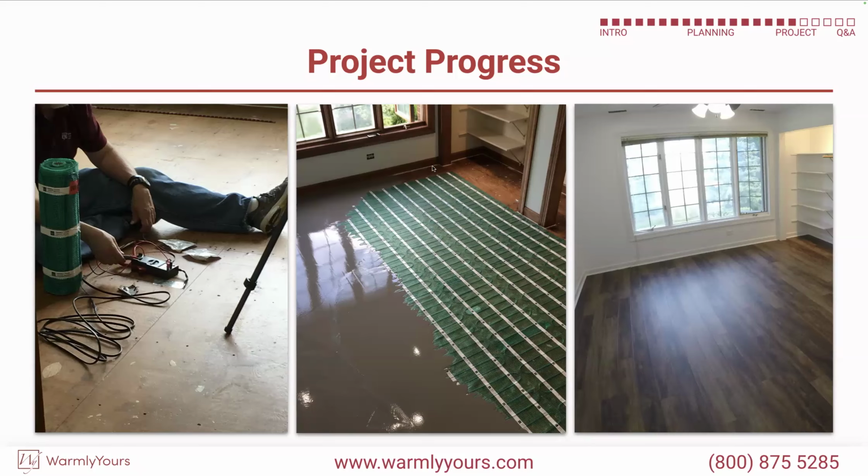Also, you can see the white line going around the room, around the perimeter. That's that caulk line we talked about before to keep the self-leveling from going down inside the walls. And remember, this product has been very well attached to the subfloor. Now, when you put the self-leveling down, you never change the way it's mixed. You always mix it exactly as it shows on the bag.